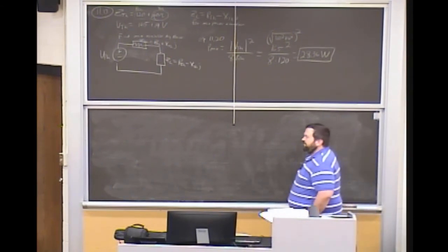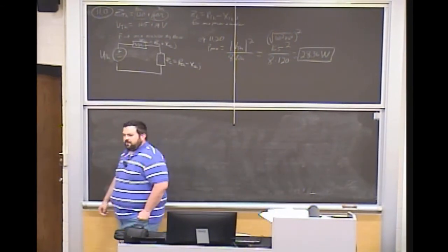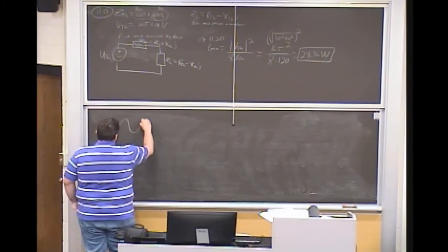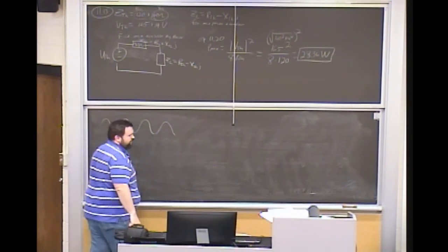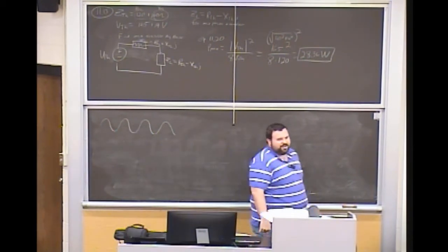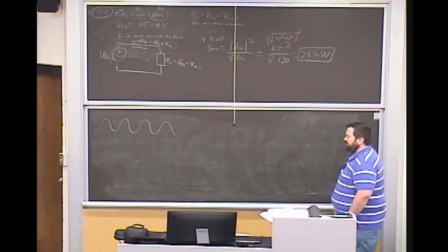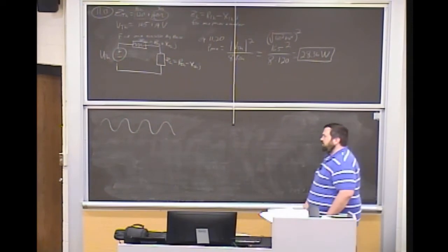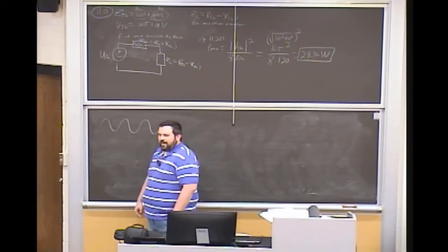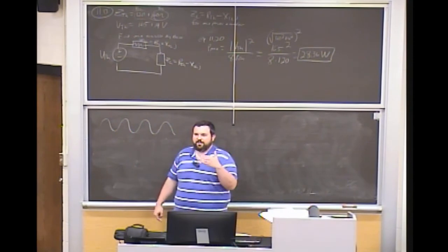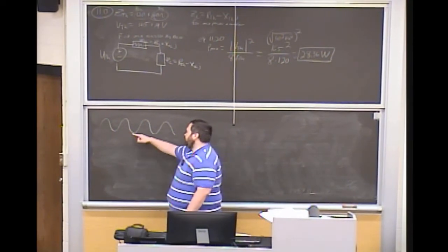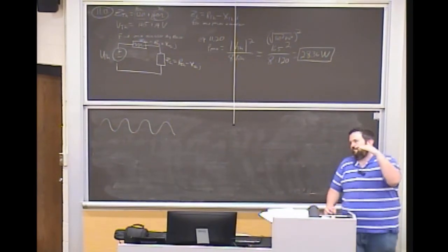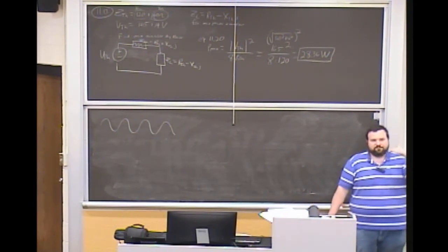Effectively, if I'm trying to figure out how much power, let's say a sinusoid, is delivering, the RMS value is the signal that, if I just held a constant DC voltage at that value, I would deliver the same average power over time. Okay? If you remember, when I had a sinusoid, at its peak I have a maximum positive power being delivered, typically.